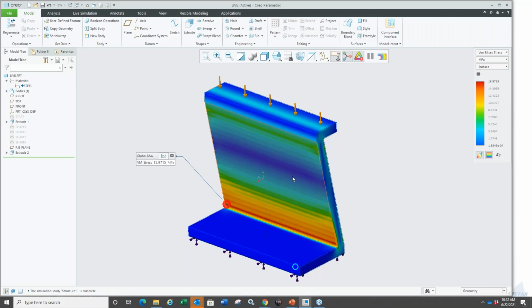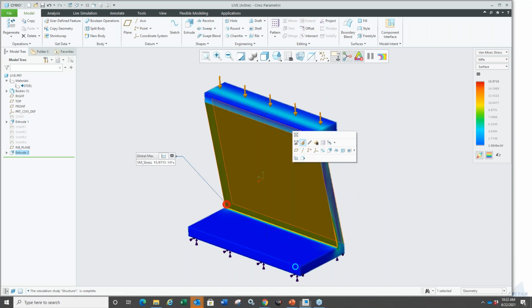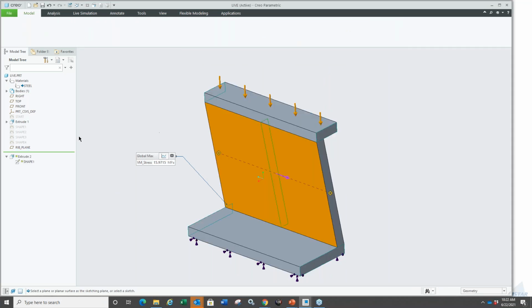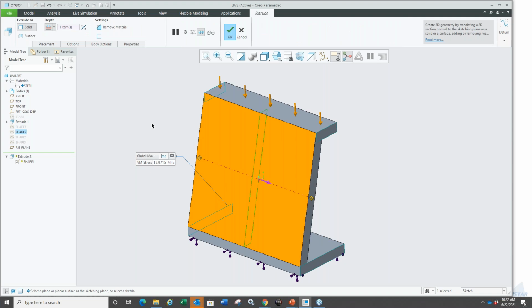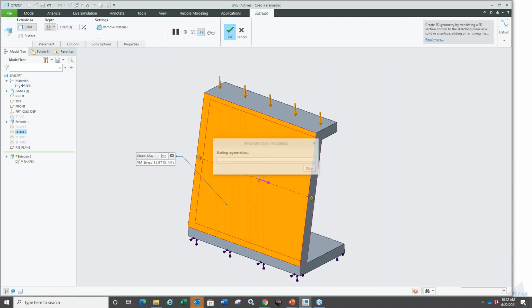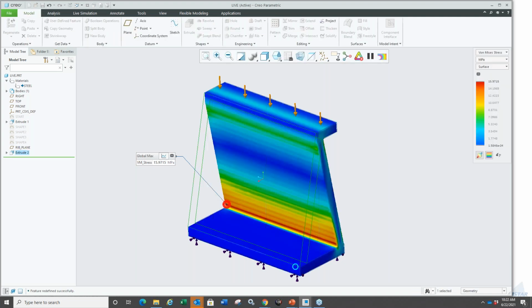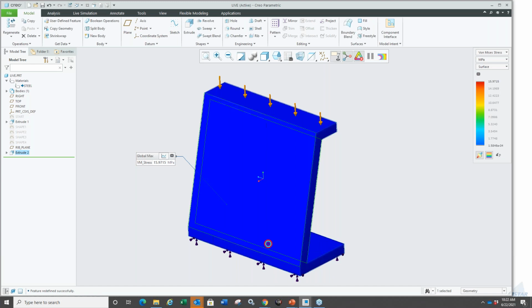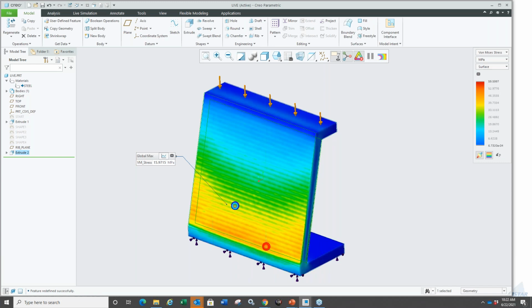And I'm thinking instead of this design, maybe I would like to redefine that and maybe use the second shape, which is shape number 2, right? I just switched that. As soon as I'm done with it, seamlessly the software or simulation kicks in, right? The spell checker that I kept mentioning, it's telling me, okay, you made the change. It goes back to blue. It runs it in real time, and it tells me that the stress is now obviously higher, right?